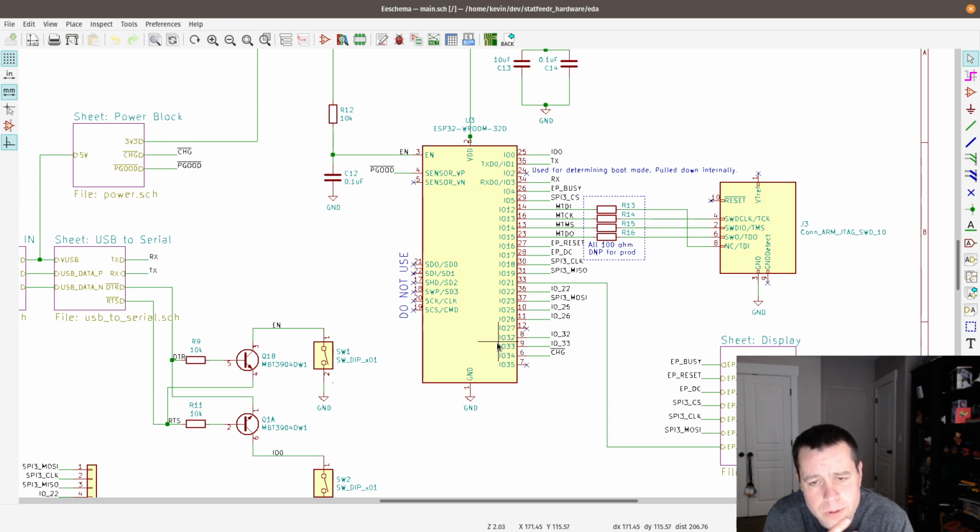you'd have to account for that in any sort of logic that was just doing a straight analog to digital read. And as I've talked through it just now, I was about to say, why wouldn't I just plug it into an ADC pin and call it? The other thing I'm a little worried about is the current that it will require. But if we use high enough resistors, the current draw should be in the microamps, negligible. And then we'll just always have the battery voltage. We would divide it, right?